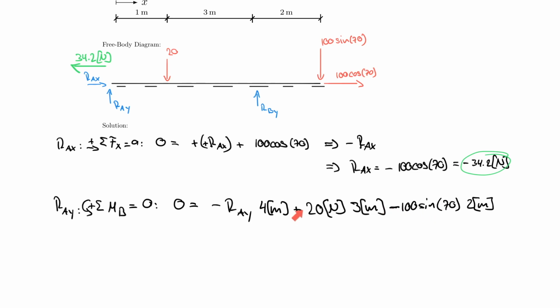And so you can see here that this sign is not affected by the direction of the force, and by direction I mean the y direction. It's really dependent on the rotational sense. You can call that a rotational direction as well, but this one here turns about this point clockwise, negative, and this one turns counterclockwise, positive.